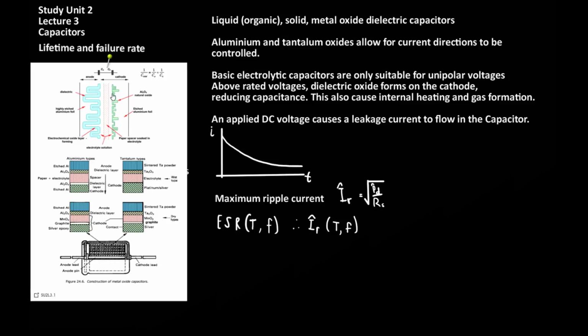forming the anode. The paper dielectric soaked with electrolyte will be combined with a piece of foil which has aluminium oxide etched onto it to form the cathode. This structure can then be either stacked or wrapped to form the capacitor, which is eventually packaged.